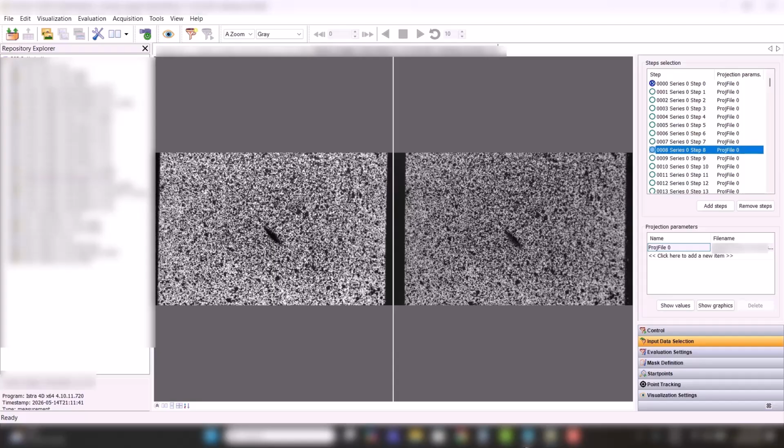Now, to really understand the fundamentals of how rung steps are used and what they do, which will be helpful for understanding how rung steps are applied to help with the correlations of speckle patterns in necking regions that we're going to talk about in a few minutes: it's not like rung steps are only applicable if you're acquiring 1 million images, or images acquired over a week time span. No, it's strictly about the difference from one image to another under whatever the circumstance.